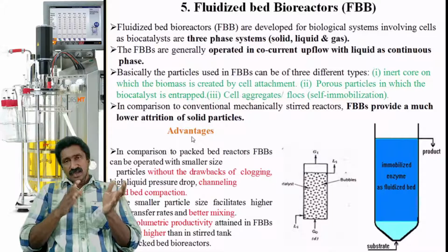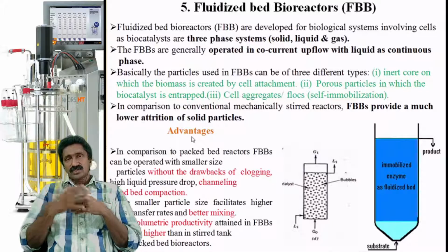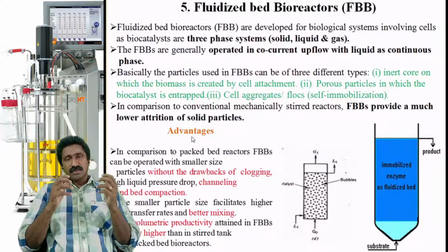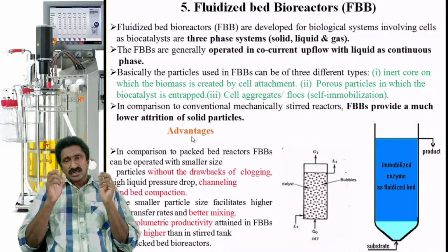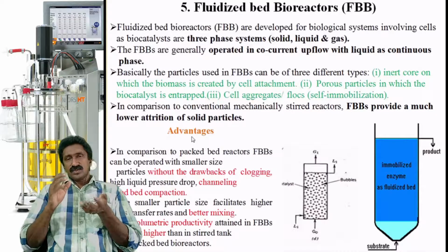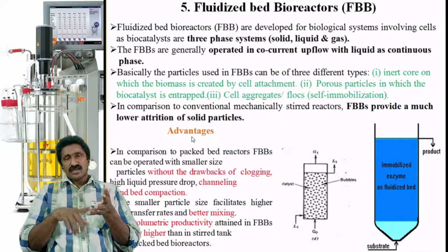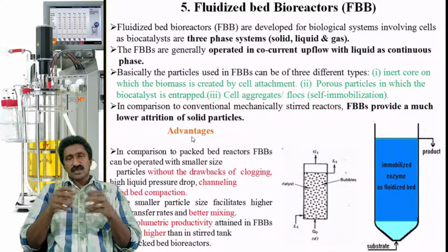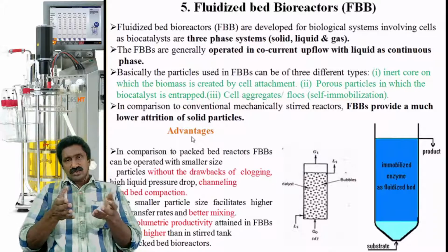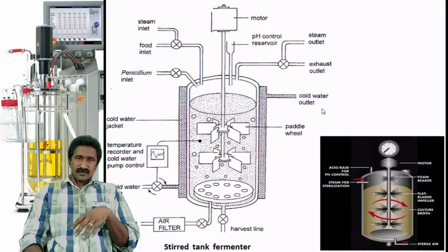So when we compare packed bed and fluidized bed reactors, fluidized bed reactors are more advantageous in terms of better mixing, better volumetric productivity, and more stability against drawbacks like clogging, channeling and bed compaction. Such problems are eliminated in the fluidized bed, so it can be considered a better model than the packed bed reactor.